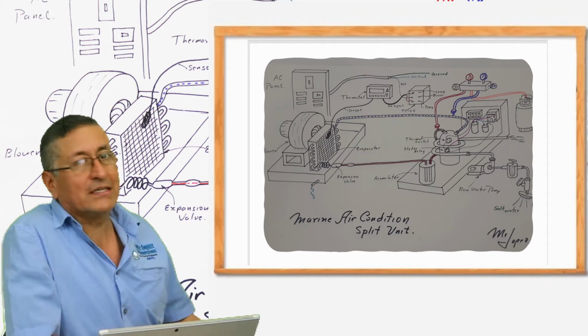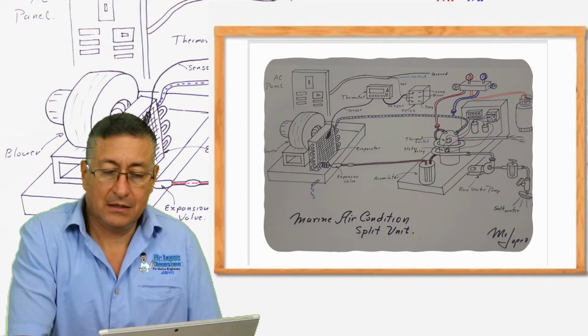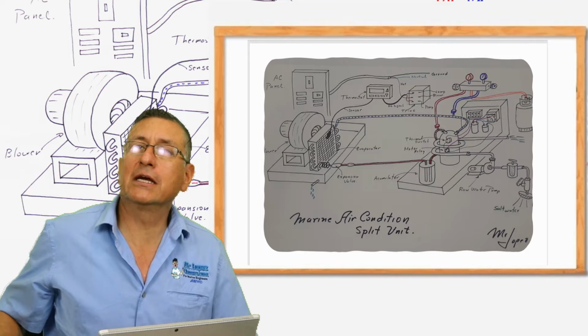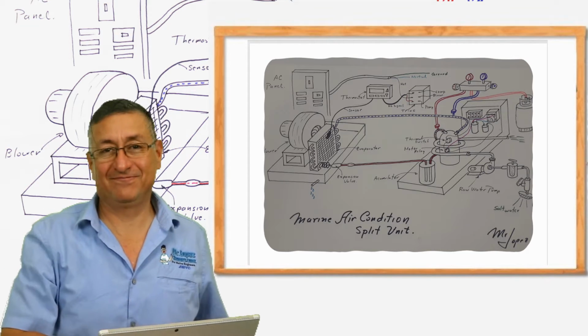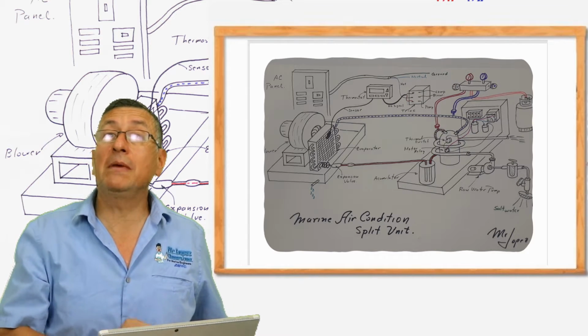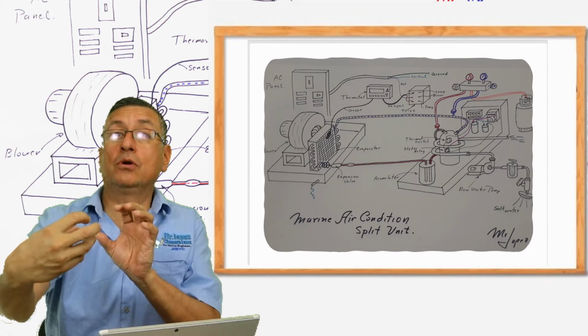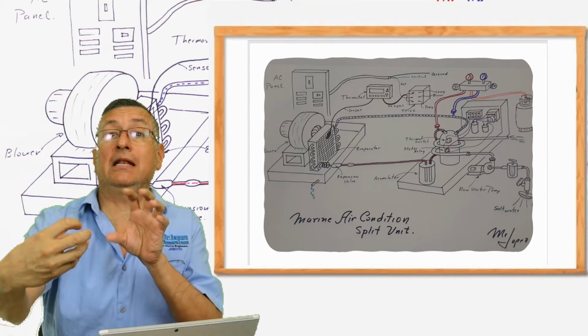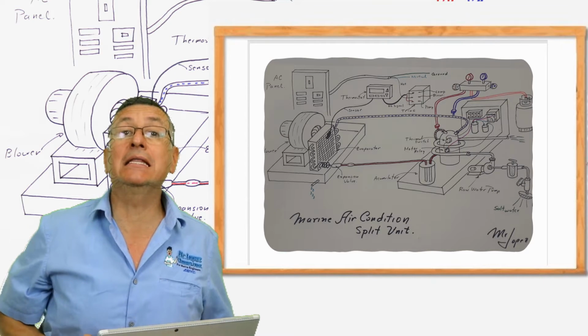In one portion of the cycle it absorbs heat, in the evaporator or in the condenser? It absorbs heat in the evaporator. Because it absorbs heat, the air at ambient temperature leaves its heat there and passes through to the other side with less heat.